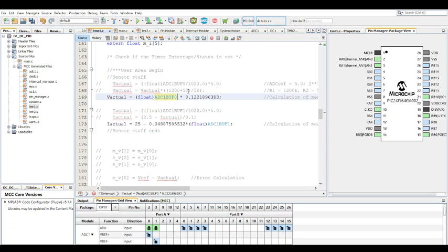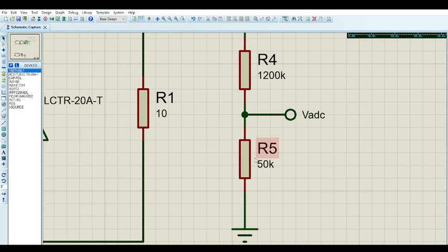Because can you imagine this resistance just going to like, it actually increases, going to like 60 kilo ohms? Because when they get hot, most of the time the resistance increases. This goes to like 60 kilo ohms, and then your reading is wrong, and then your converter's output voltage keeps increasing because it's seeing something wrong here. So always try to choose a resistance value right here that's large. No, sorry, not small. Large.